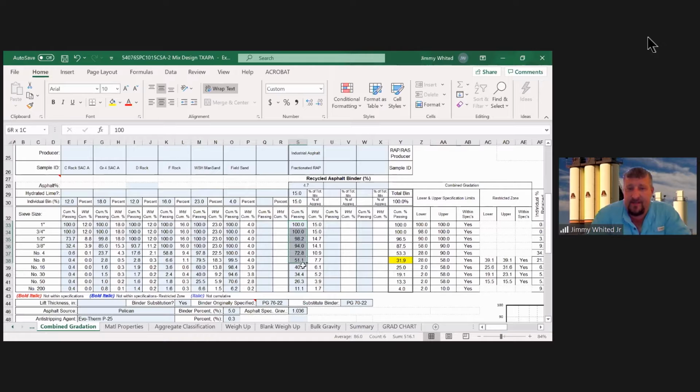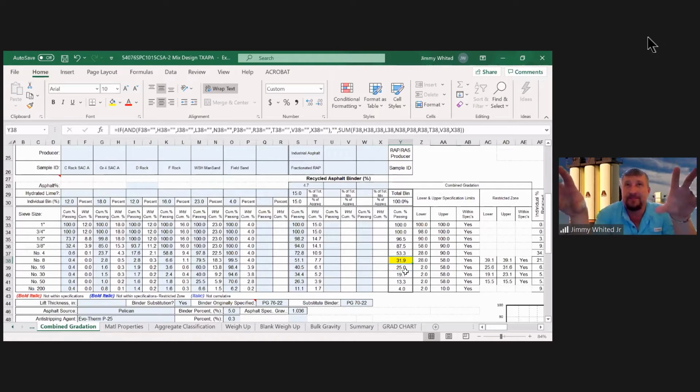Everybody's aggregates, like Ryan said, most mix designs were already close. So if you take your old mix designs and don't worry about these other sieves, by just adjusting your number 8 sieve, which typically is going to be your F3, your man sand, your field sands, and just pushing those up and trying to control this one, it will automatically control your top, and then it will automatically control your bottom.